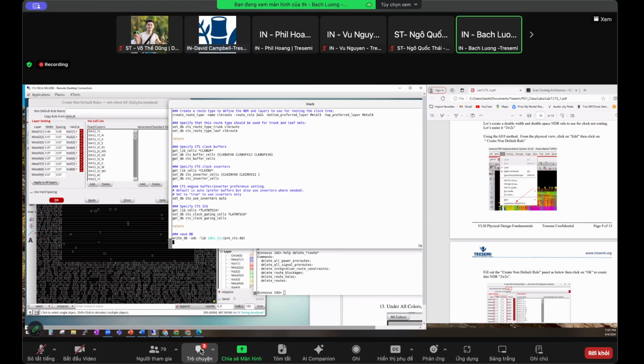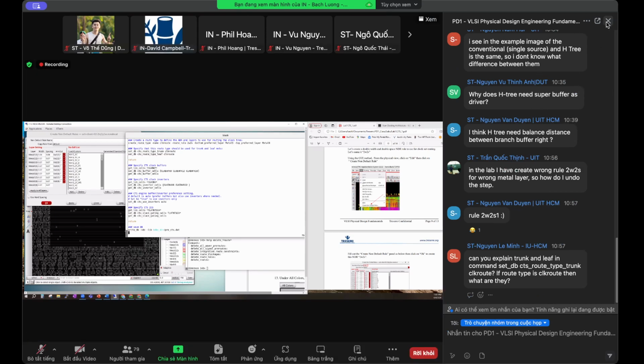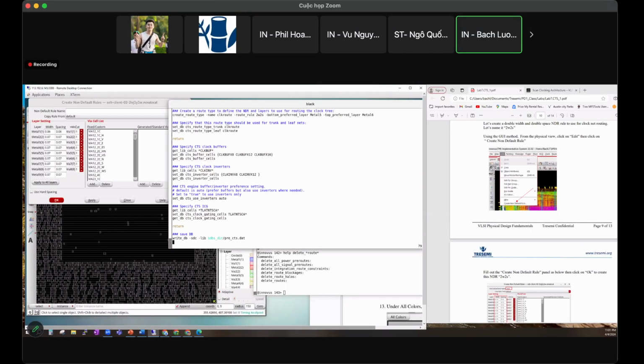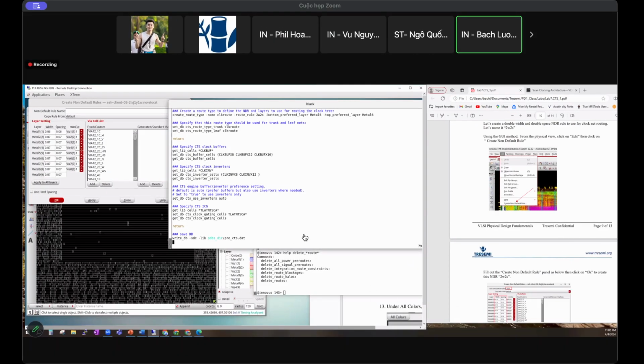Yeah, so clock tree synthesis is a very important step, okay? Because if you build a bad clock tree, it will affect your project coming up at the end. Each student will do your own project, and we have constraint targets for your design performance. If you build a bad clock tree, you're going to have a hard time closing your hold times and meeting the target performance.